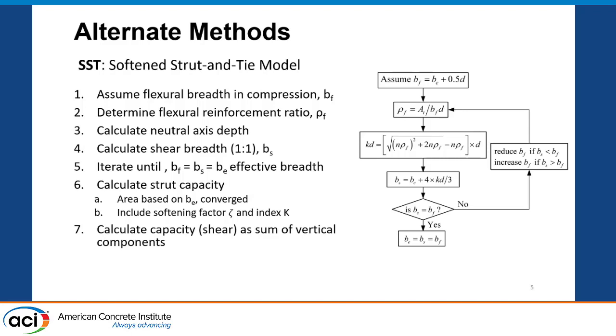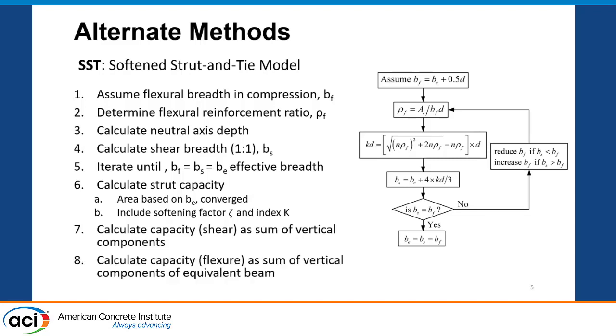In our case, you have 3 inclined struts. You'll calculate the compressive capability of those struts. And then using theta, the inclination angle, you'll calculate the vertical contributions and calculate the corresponding ultimate load. And then you'll do a similar thing for that equivalent beam that we have. You'll calculate the capability of that equivalent beam in flexure, and then you'll calculate the contributions from the three parts.